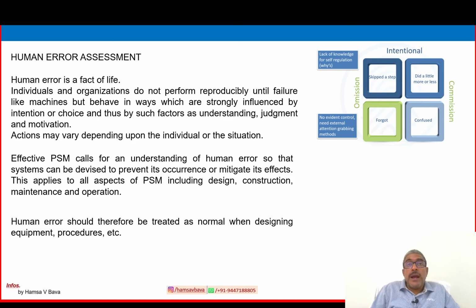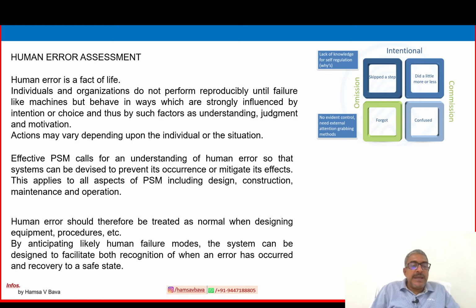That's why standard operating procedures, protective systems, safeguard systems, and shutdown systems are installed in the process and the equipment. By anticipating likely human failure modes, the system can be designed to facilitate both recognition of when an error has occurred and recovery to a safe state.